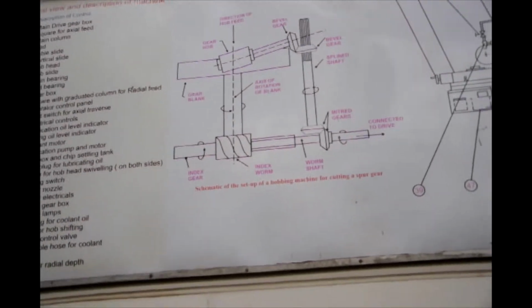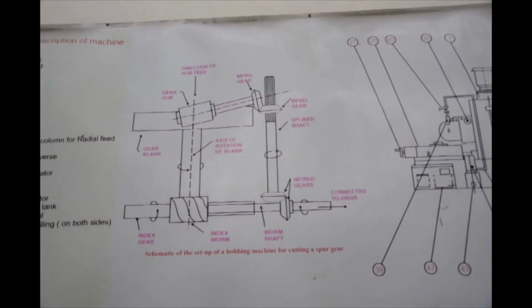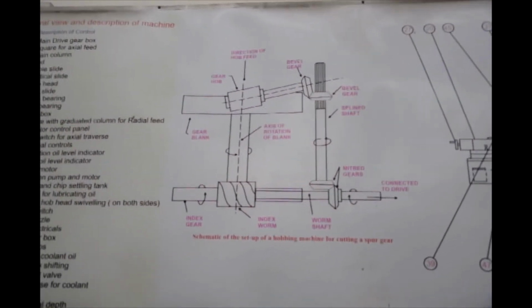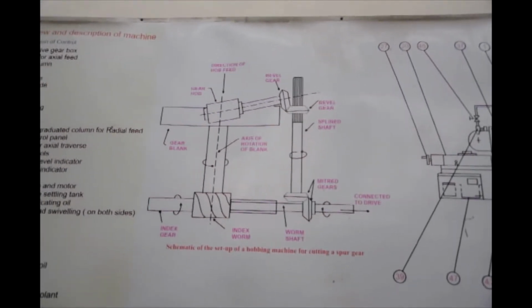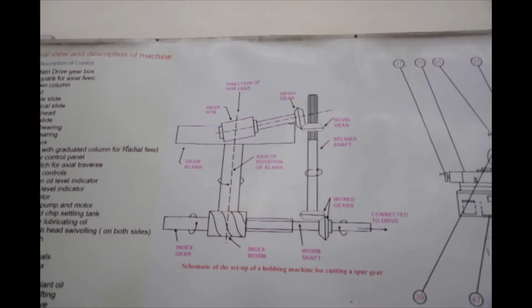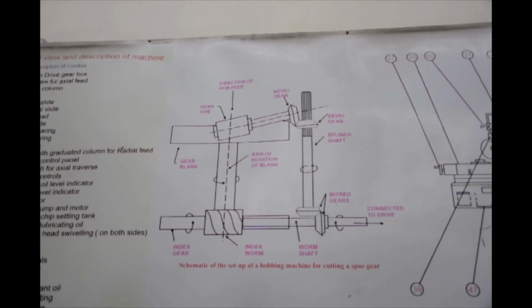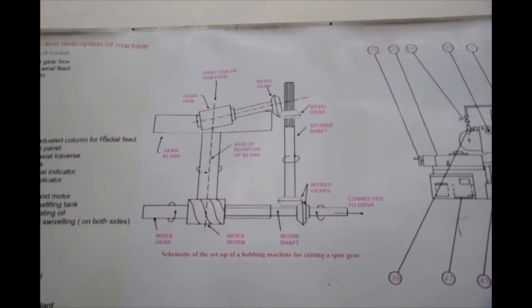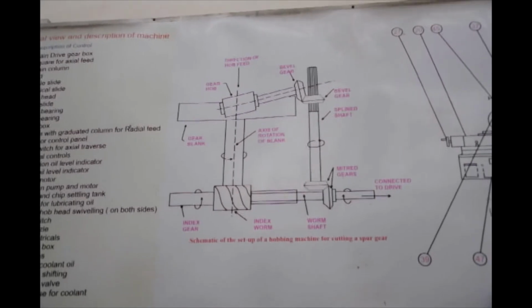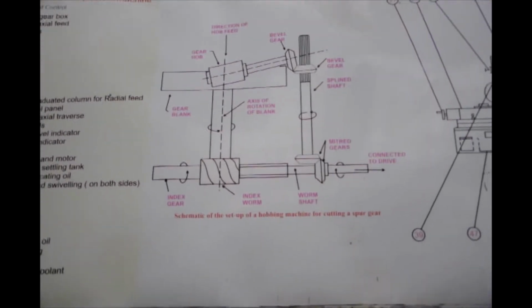There are some starts in the gear hobs, and gear hobs are again module specific and helix angle specific. So that is why it is a costly affair, but once it is done, mass production can be implemented. It is totally an example of mechanization. Only the electrical part for the driving is there, and everything else is implemented mechanically. There is a CNC hobbing machine with many flexibilities, but that is pretty costly.